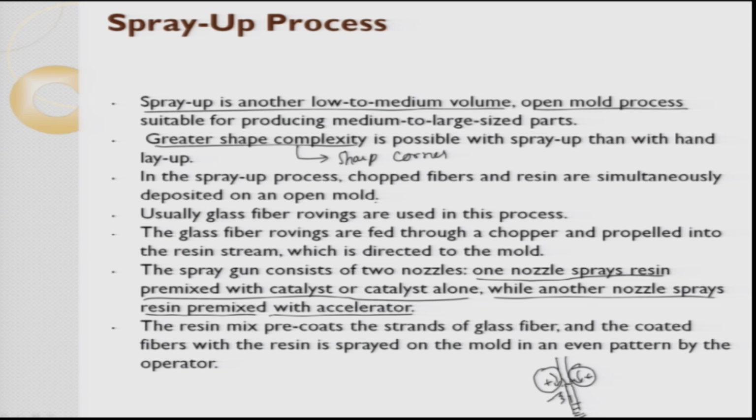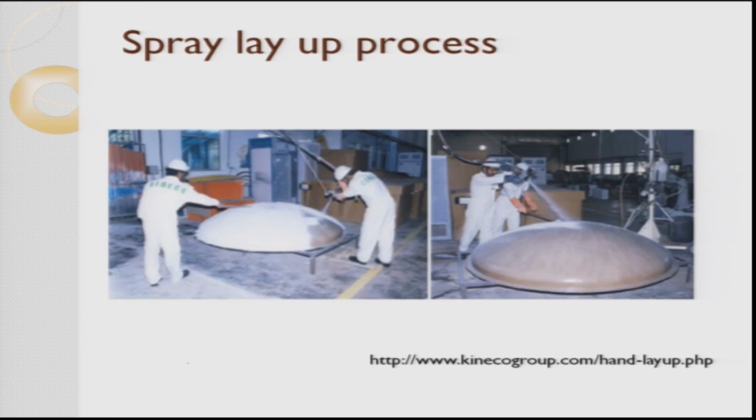So the resin mix pre-coats the strands of the glass fiber, and the coated fiber with the resin is sprayed on the mold in an even pattern by the operator. So it is also a skilled process depending upon the operator.